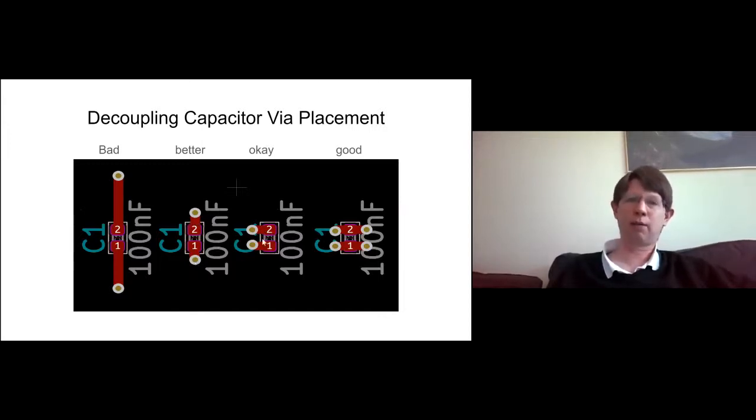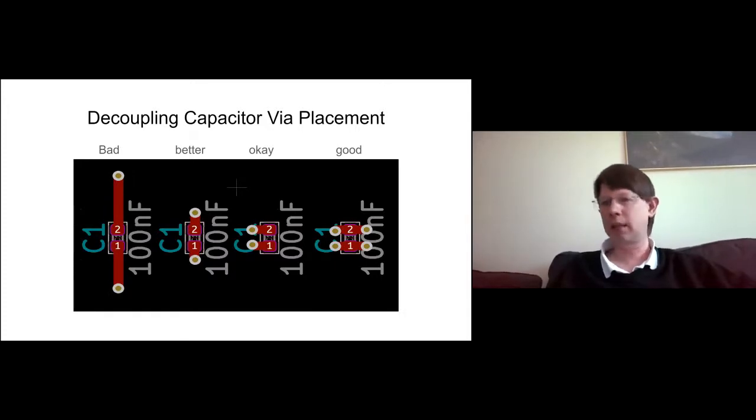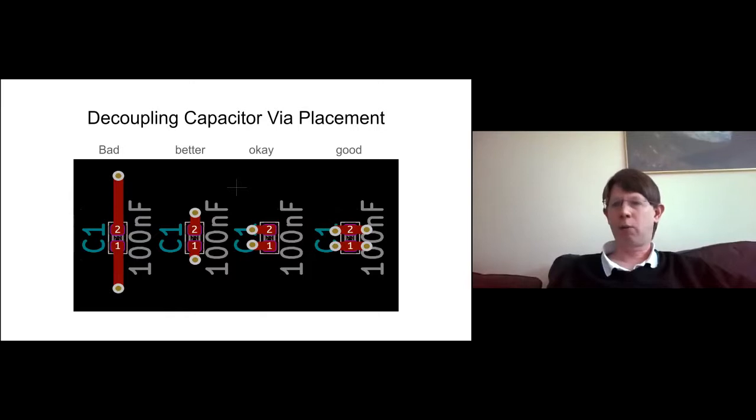If you do the maths here on the loop areas, and the loop area is important, you have to consider the three-dimensional side of the loop area. I'll come on to that in a second. And you can do even better by putting 4 wires on your capacitor. Wires are often almost free in circuit board design these days. So here we have 1 loop and 2 loops, so we have 2 loops in parallel, and that actually means we have a much lower impedance for the wire placement and the decoupling. So we get better frequency response.